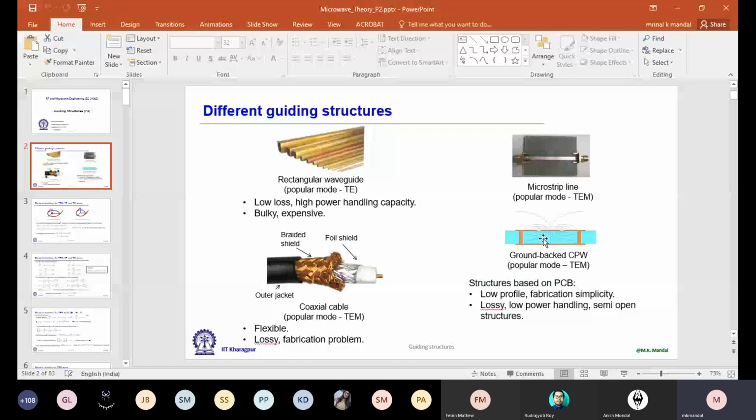Well, and PCB technology simply becomes compact. It's a two-dimensional structure. So for microwave PCB, loss is one important issue. The PCBs or the substrate material or the dielectric material that we use at low frequency, let's say at kilohertz or megahertz, we can't use the same thing at microwave frequency.